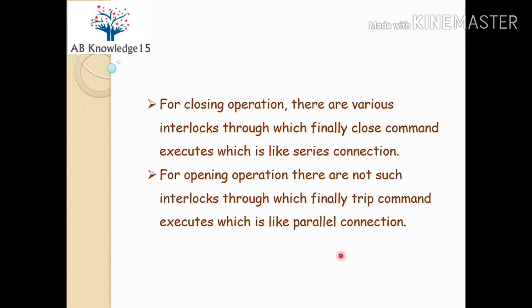For closing operation, there are various interlocks through which finally close command executes, which is like series connection of breaker. So in the closing operation, there are interlocks like a spring is charged or not, a numerical relay is healthy or not, master trip relay is reset or not.